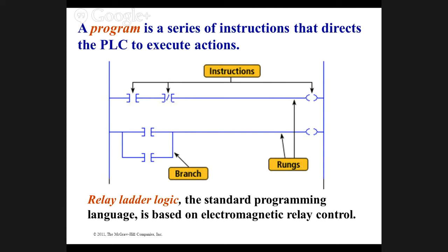Well, in order to facilitate all these old school electricians, in order to get them to program the PLC, they designed the software to look just like the logic diagrams they were used to writing and working on. So instead of working on paper, they work on the computer or the program. That makes sense? So it's pretty simple. It comes with instructions and outputs. All right? Inputs on the left, outputs on the right. And those are the rules for RSLogix 500.